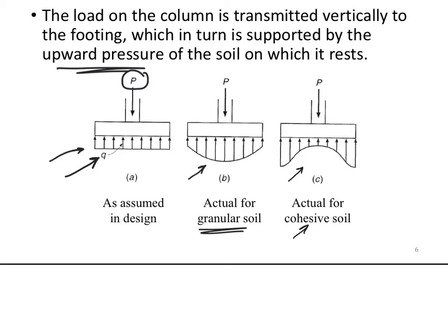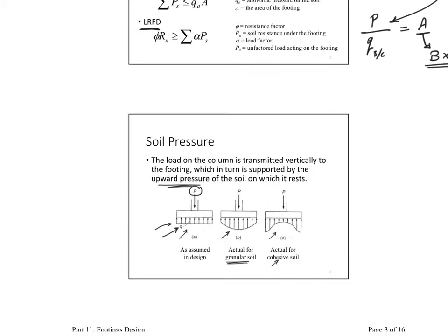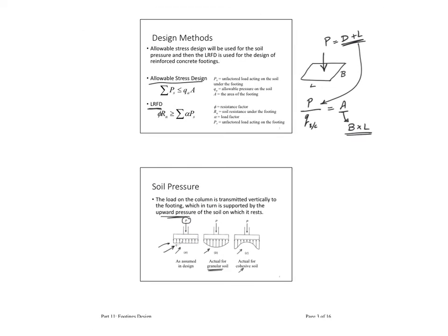You'll have sand and a little bit of silt, a little bit of clay. As you go geographically in different places, you'll have a combination. So as designers, what we end up doing is we just assume a straight line relationship. And any differences will be taken out within our safety factor assumptions.